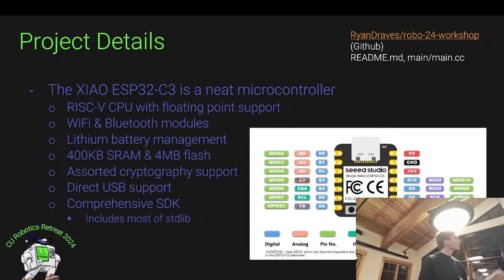Okay, let's talk a little bit about this ESP32 module. This C3 variant of it is a neat little microcontroller. If any of you hail from UC Berkeley, anyone? All right, that's all right. Their little pet project is integrated into the system here. It has a RISC-V CPU, so it uses a fancy new instruction set that does things, I'm sure. It has a nice floating point module as well. That's not something you always get with embedded systems. You don't always get access to floating point operations. Sometimes you're in integer-only land. It has integrated Wi-Fi and Bluetooth, maybe a little bit fancier than floating points.